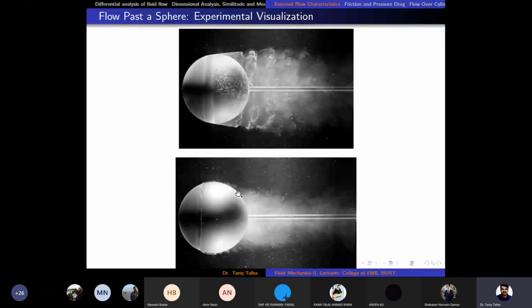And that is also the reason there is a phenomenon of reverse swing in a cricket ball, because in that as well, one side of the ball is kept shiny and the other one is made rough. On the rough side, the flow becomes turbulent and the boundary layer remains attached, and on the shiny side, the flow remains laminar and the boundary layer separates somewhere here. So there would be a lateral pressure difference as well. That's why the ball moves in air.